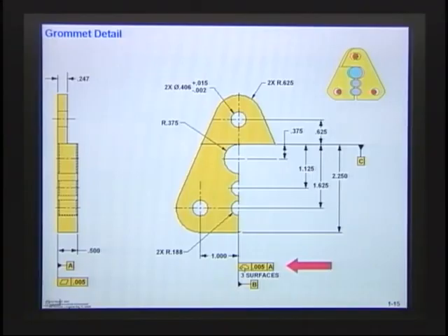So by putting a profile on, I have a tolerance zone, and a tolerance zone is a band of tolerance. Well, let's see if I can draw that band of tolerance here. It says that I have a perpendicularity zone, and the perpendicularity zones are in line. So I'll show that tolerance zone, and it's kind of hard to see there, but there's my tolerance zone. I have a band of tolerance, and the surfaces then have to fall someplace inside of that zone. And again, why I showed a tolerance there of 5 thousandths was because, remember, the mating part comes up to this, and in this area right here, we couldn't have a gap any more than 10 thousandths. So I put profile on this within 5 thousandths. The other one had 5 thousandths. That's going to give me a max gap of 10.